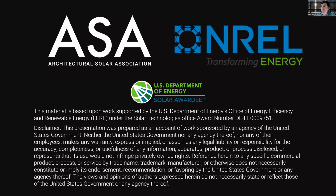Right now, there are rapid shutdown standards being developed in the US. Those standards have mainly been focused on rooftop solar and the ability for a fireman to interact with a solar system. In rooftop applications, it makes a ton of sense from a rapid shutdown perspective, because you don't want firefighters interacting with solar panels on a roof where they may need to vent it. On a facade, it's a different question, because firefighters don't necessarily regularly vent facades or interact with facades in the same way. I think fire protection in facades, from my perspective, really needs to be more focused on the risk of the solar system arcing and causing a fire, rather than being safe to deal with by fire personnel.